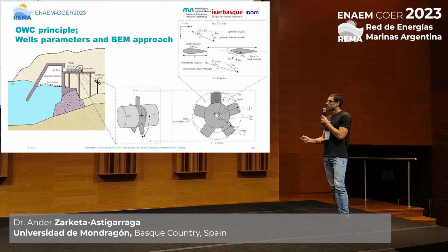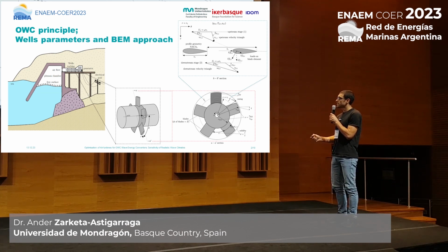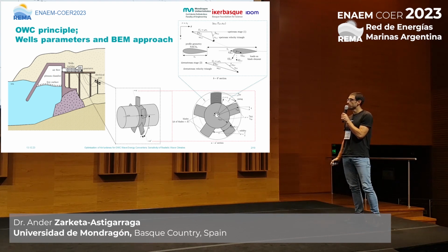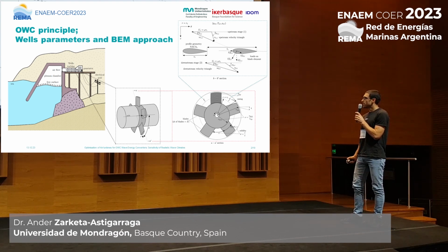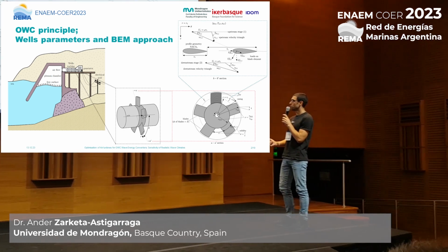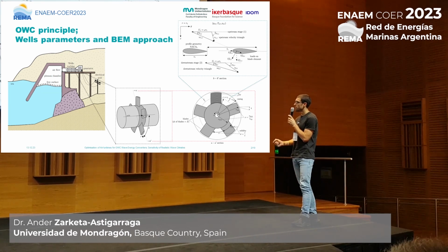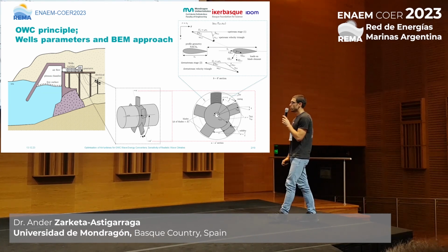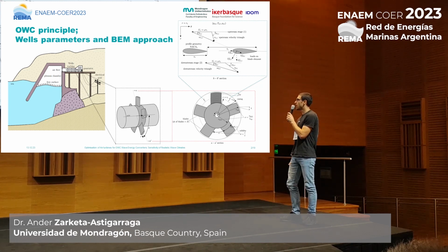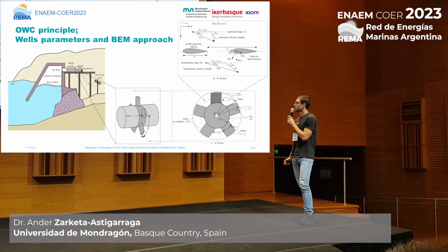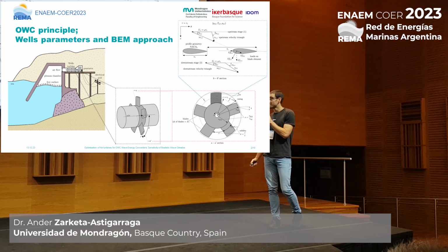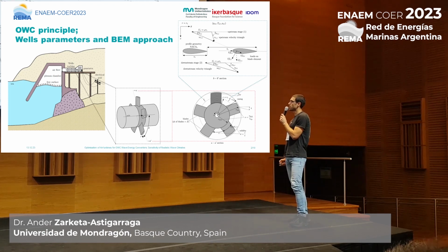So that is the framework, and precisely we will be dealing with a Wells-type monoplane turbine, like the one shown in the bottom left-hand side figure. We will be optimizing the geometrical parameters of such a turbine that are shown at the rotor plane, which I'm showing at the right-hand side here. There are plenty of geometrical parameters that enter the design: the number of plates, the solidities, the hub-to-tip ratio, the omega. All that will be introduced in this semi-analytical code that we are developing.